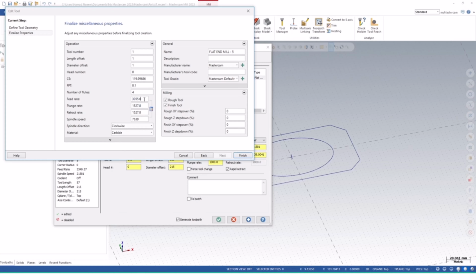Okay. So for me, I'm going to select the cutting feed rate of 1500 millimeters and the plunge rate of 300 millimeters. And the rotate speed, you can make it 3000 because it will always rotate at a very high speed.